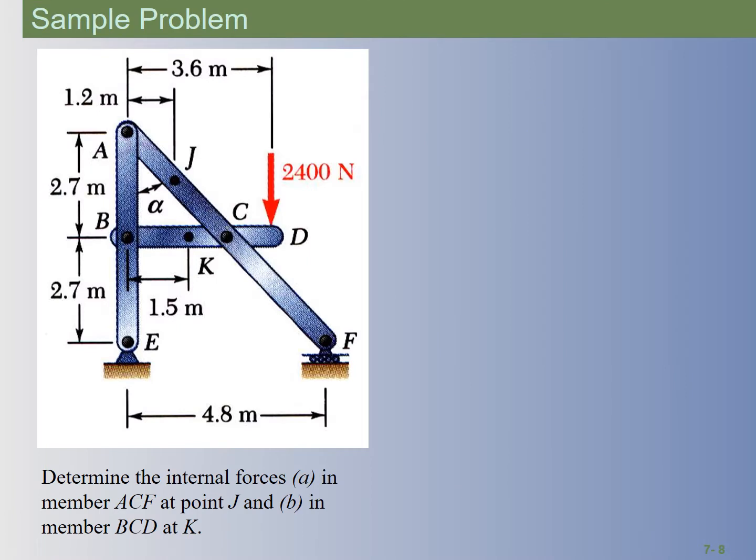Let's go through some example problems. So here we have a frame and we've got a couple of multi-force members. So here we've got 1, 2, 3. We also have, this is 1, 2, 3. So they're all multi-force members, which means we're going to have bending moments, shear, and axial forces inside. Okay, so what we're going to do, determine the internal force in member ACF.